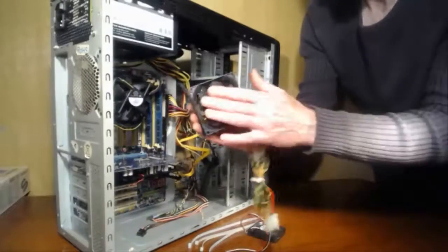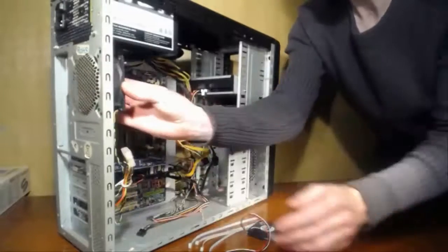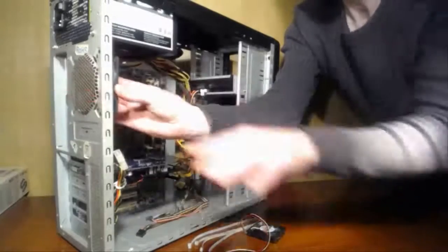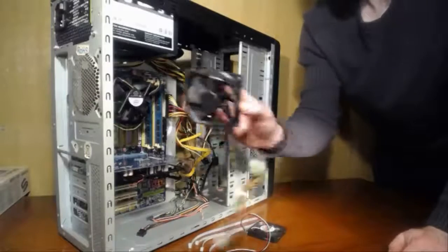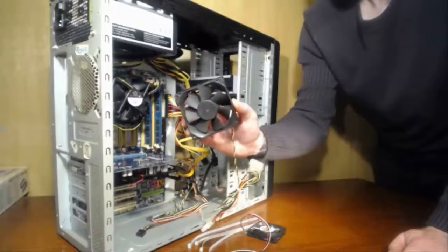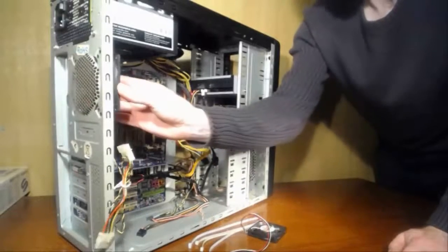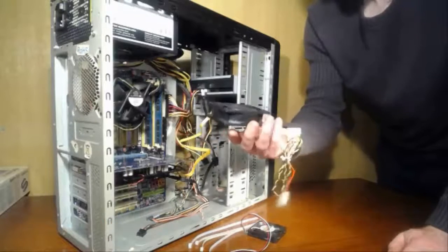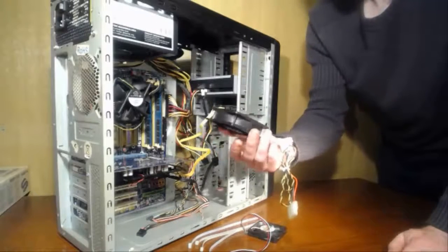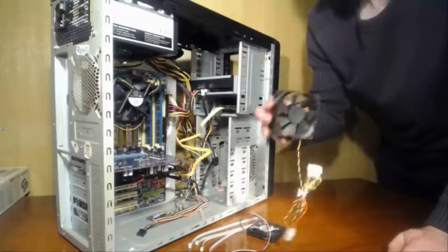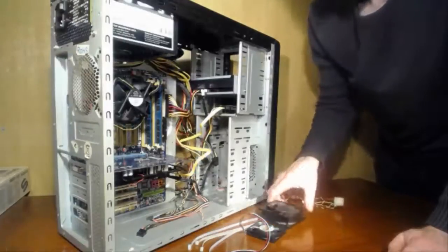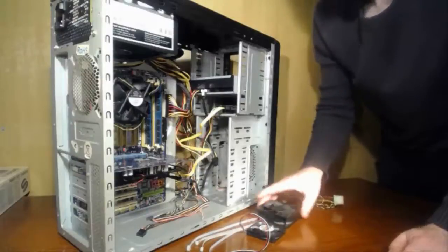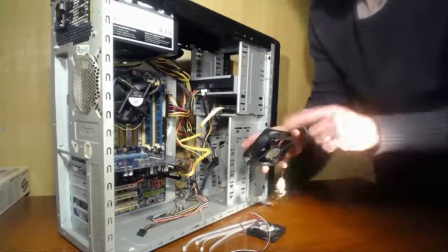You want the back fan at the back of the case to pull air out. So you'd mount it in such a way that whichever way the fan rotates will be pulling air out. Again, you will see this in the instructions with the fan. It'll come with information about which way the air flows through it when it's turned on.